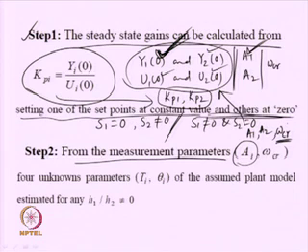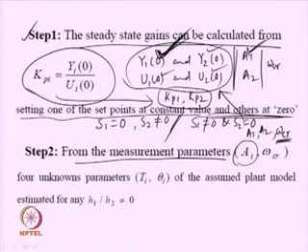That means, with the use of CN1 and CN2, we have been successful in eliminating the ill effects of interactions between the loops, or the loop interactions have been nullified, and subsequently it is possible to get the 2 loops having outputs with the same frequency. Okay. So, this is how we make 7 measurements, and we are now able to estimate all the parameters associated with the transfer function models.